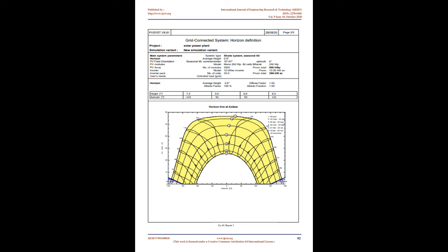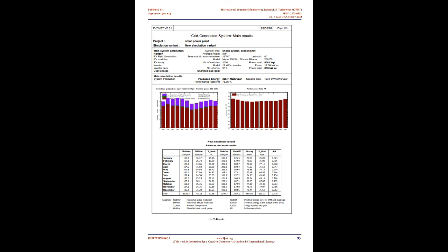The horizon, or far shadings part, is the simplest way for defining shadings in PVsyst. But this is only suited for treating shadings of objects sufficiently far, as we can consider they act on the PV field in a global way. At a given instant, the sun is or is not visible on the field. Typically the distance of these shading objects should be higher than, say, 10 times the PV field size. Defining a horizon profile is a very simple operation with the